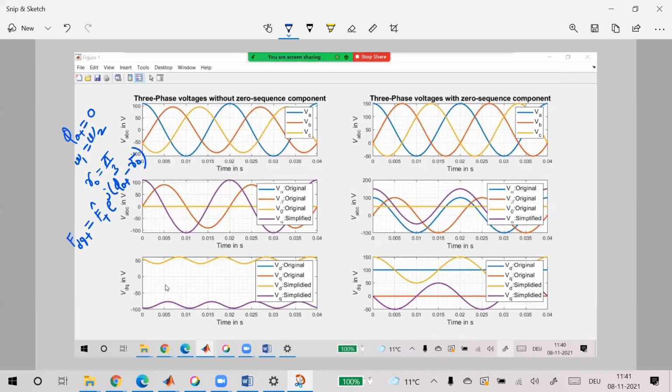Yeah, because our delta we have kept as pi by 3. If you see the MATLAB script, this difference is basically going to be minus pi by 3. So we have plus e power j minus pi over 3, right? And you can find your positive sequence. So your FD is going to be F cap cos pi over 3, and your FQ is going to be minus F plus sine pi over 3. Why do you get minus? You know this Euler expression, right? E power j theta is your cos theta plus j sine theta.